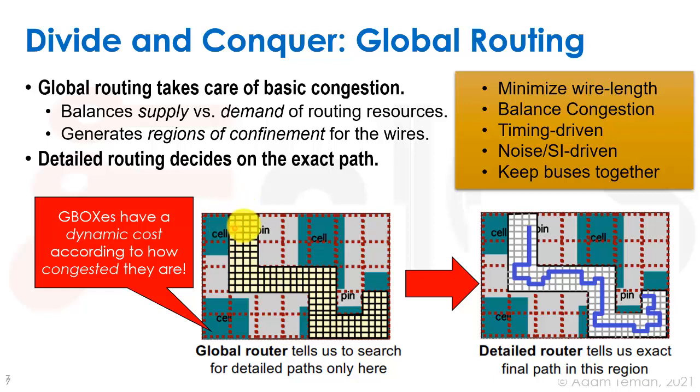Now, after we did it for all of the nets, we can go and look only at this box. And that's a much more bounded problem. It's a much simpler and smaller problem. We have many fewer nets to actually detail route, and then we can route them in a detailed fashion. Well, if we take one of these boxes, for instance, in the middle of this net, we would say where it crosses over into the box, that's going to be the source, and where it goes out of the box is going to be the target. And now we just have to maze route with detailed route and fixing DRCs inside this G box. And in the end, we'll connect them all together, and we'll get the actual detailed route of our long net.